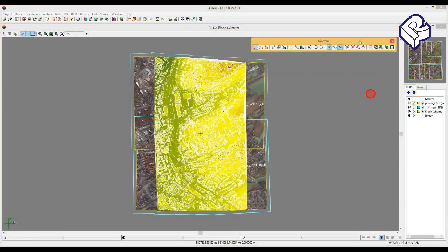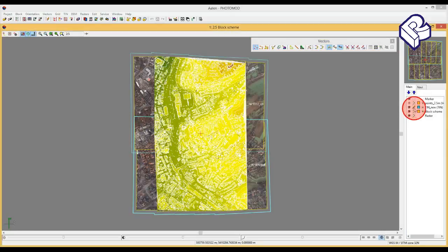As you know, there are some kinds of digital representation of a terrain. Digital terrain model, which shows just heights of raw relief, and digital surface model, which represents not only natural relief, but also heights of trees and artificial objects. On the base of the existing TIN, we have been able to build DSM already. Build them from TIN.